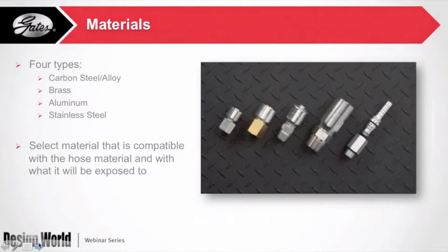Brass, not quite as prominent. It's made for generally a lower pressure or something where you need some corrosion resistance. A lot of times for fuel lines and that sort of thing where you don't want a spark to occur as well, you can see brass. Aluminum, very lightweight, obviously, for lower pressures as well. The lightweight, ease of handling, it's not a big heavy coupling, so it's easy to put on the end of a very light transfer type hose in most applications.